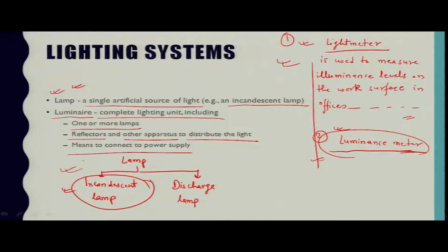It operates by electrically heating a filament that produces radiant energy, some of which is in our visible spectrum. The common material for this filament is tungsten. A discharge lamp produces light by means of an electric discharge in gas. Discharge lamps are generally more complicated because they require special controls to provide the conditions under which discharge is initiated and sustained.